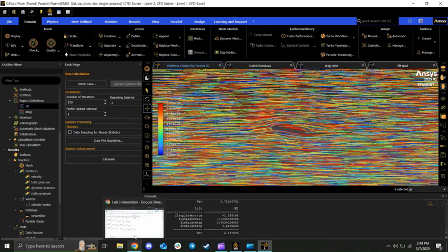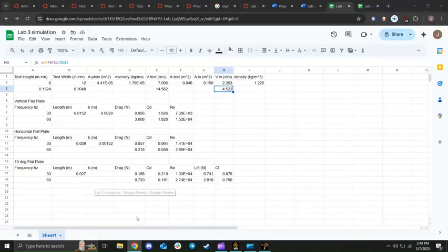So to find the coefficients, we would have to use the formula for coefficient of drag or coefficient of lift, which is the force divided by 1/2 rho u squared times A, with u being our velocity in the test section. Since this is a 2D flow, instead of an area, it is just the length being affected by said force.